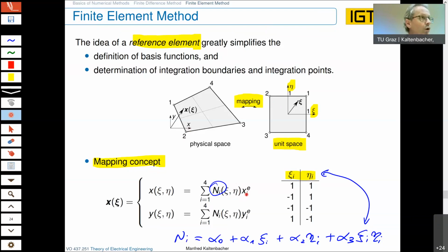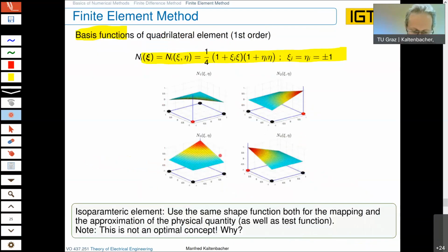So you see, also in this simple case for these 4 nodes, these basis functions or shape functions, interpolation functions we compute by this ansatz need this local support. And that is given here. You can just make this plot in MATLAB or Python or wherever you like.